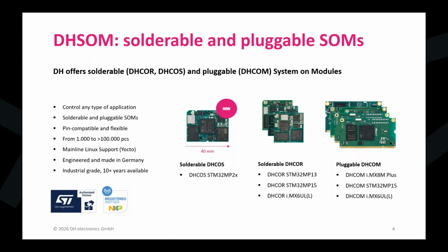One important example within our solderable portfolio is the module based on the STM32MP2 platform, and this module combines the flexibility of pin compatibility with a space-saving solderable design. It features an architecture combining application and real-time processing cores, enabling a clear separation between application processing and real-time or security-related tasks. The module integrates LPDDR4 memory, eMMC, SPI boot flash, Gigabit Ethernet, and optional Wi-Fi Bluetooth connectivity.